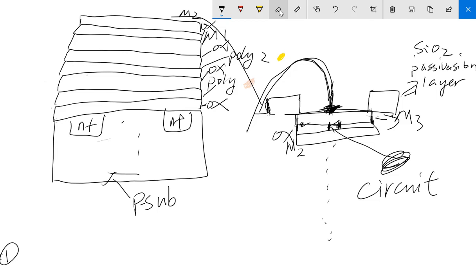So actually, if I only have a metal 2 to metal 3 contact, it's going to be a hole here, but there's no metal 3 layer really laid out over here. The reason is, you can imagine that for metal 2 to metal 3, you have all these holes. And if you have a metal 3 layer on top, I don't think it's going to stay there because it's the same size, and there will be a lot of holes, and the metal 3 won't stay there.